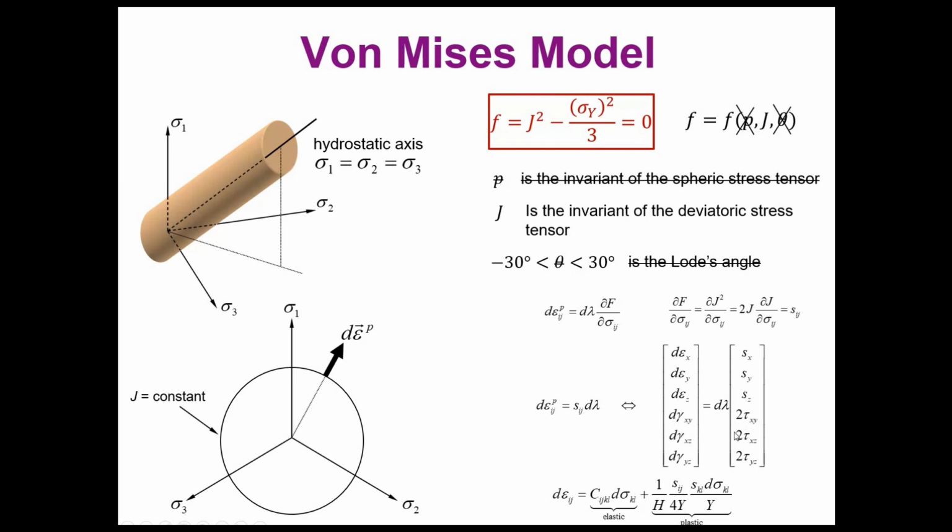In matrix form you can see the calculation of the plastic strains, and there is an expression in here just for you to have an example: the total strain is going to be equal to the elastic strain plus the plastic strain that is calculated finally with this expression in here. You can recognize that this y will be the yield strength, or the initial yield strength, or most probably the plastic one. So this will be non-linear, because this will depend on the level of strength. And this h is most probably the plastic modulus that defines the plasticity.